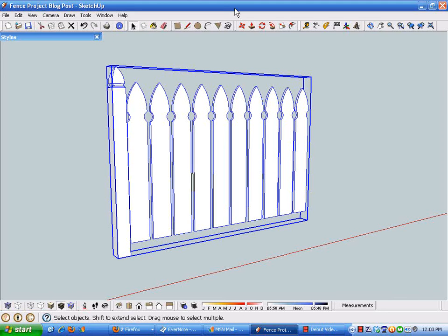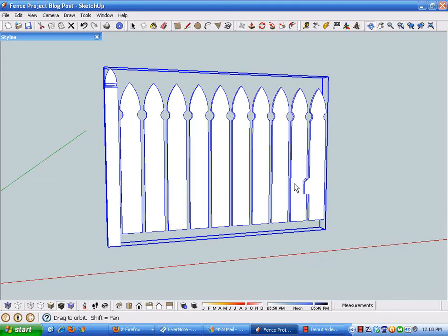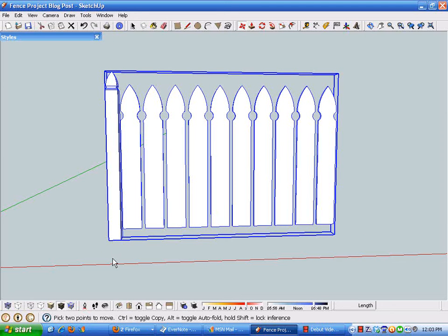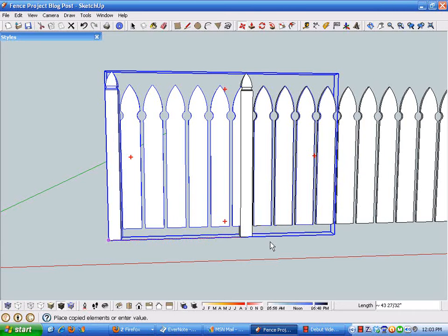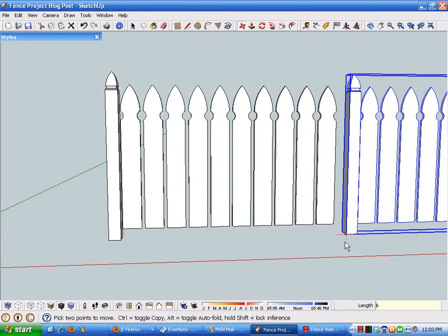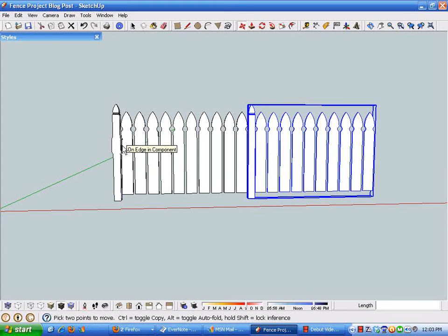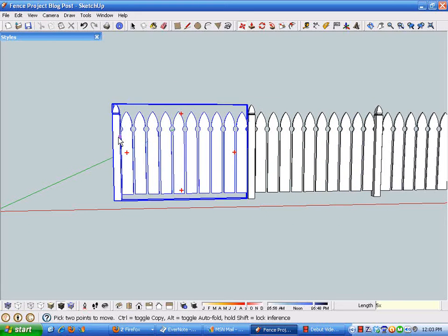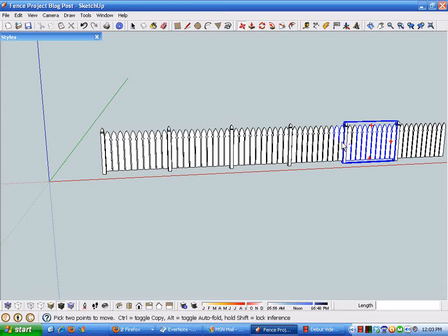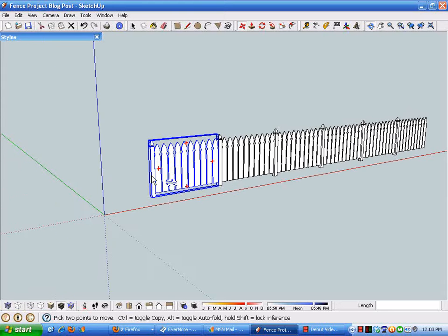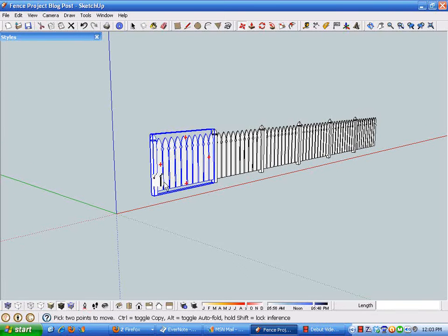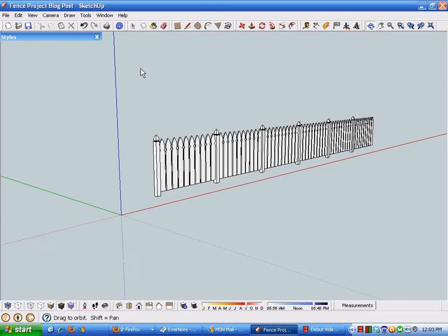So I'm going to copy that component by selecting the move tool, hitting the control key and the right arrow key, sliding this 68.5 inches will give us the same spacing as everything else, and then I'm just going to tell it to do that 5x, which will give us many sections. And I could have just as easily typed 500x. SketchUp cares not the numbers of things you care to duplicate.